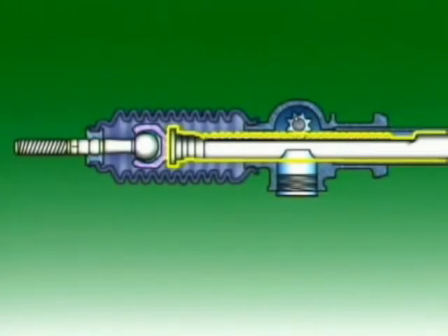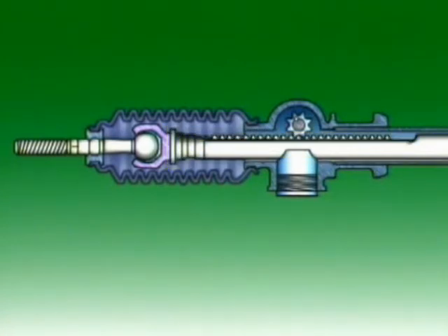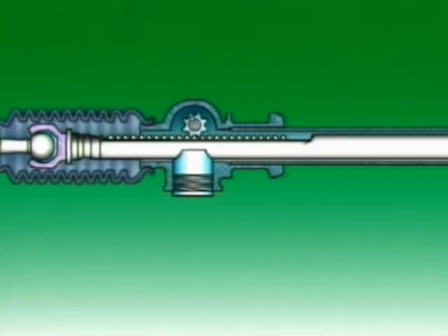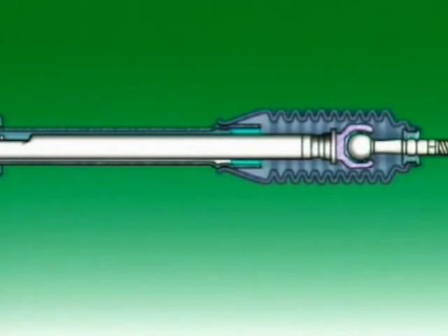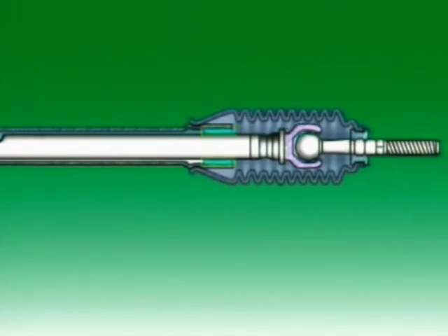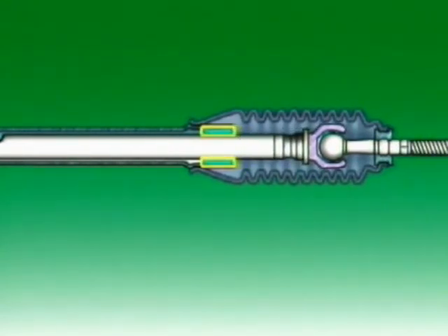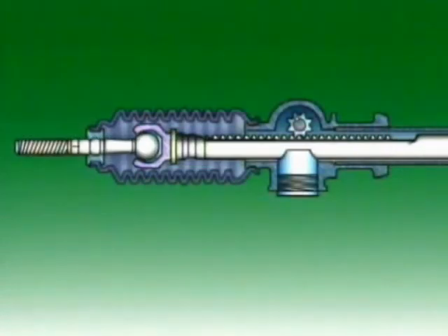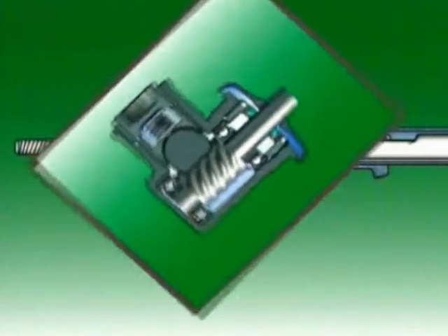The steering rack is supported at the pinion end by being sandwiched between the pinion and a spring-loaded rack guide yoke. This spring-loaded yoke ensures free play is eliminated between the gears, while still allowing for relative movement. The rack is supported at the other end of the rack housing or tube by a bush, normally of nylon. Nylon is used because it has a low coefficient of friction and low wear rate.